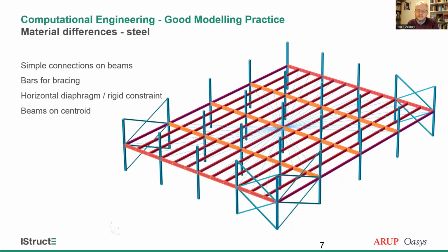to the bracing. Also, unlike the CAD programs, you want the beams on the centroids. Offsetting the beams down to the top of steel, for example, can add in some weird additional effects. So by default, keep everything on the centroids. The exact level is not normally that important. So the top of steel for the centroids is close enough for engineering in general.